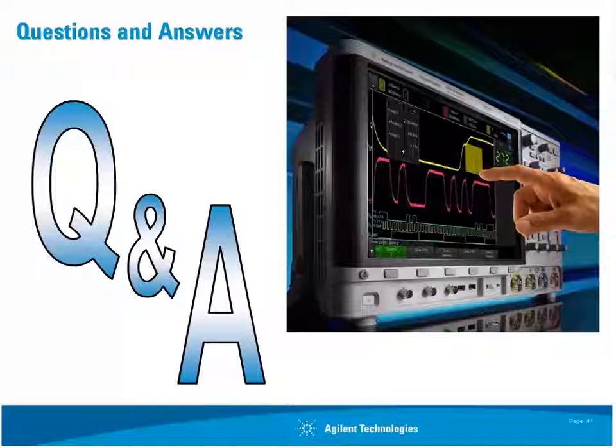In the case of this series of scopes, it's 1 million waveforms per second. But most scopes in this class have a trigger output signal, usually on the back panel of the scope. You can connect a BNC to the trigger output signal, then run it into a counter or into another oscilloscope and simply measure the frequency of that trigger output signal.